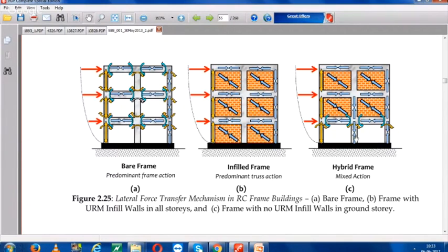How can we save against that soft story effect? You need to provide shear walls at different intervals, different places, so that the building can be saved during the earthquake when it induces the shear forces.